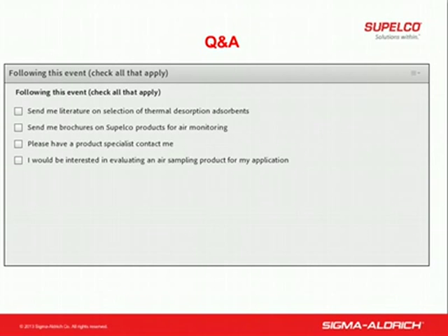And for those of you listening who have questions, now would be a very good time to send them in. So, Jamie, our first question today is, I'm looking to trap 1,3-butadiene. Which adsorbent should I use? Dave, that's a good question. There's two adsorbents that are showing a lot of promise right now, and that's Carbopack X and Carboxen 1016. There are some methodologies using the mole sieves also, but because of the moisture problem, maybe the Carbopack X or Carboxen 1016 might be a little more user-friendly.